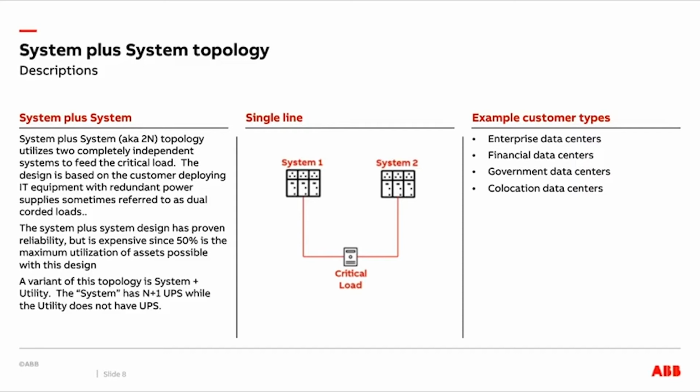Typically, these power supplies share the load equally. The system plus system design eliminates single points of failure and also allows concurrent maintainability. The major drawback is the maximum design utilization is 50%, resulting in a very expensive system. So extremely reliable and extremely expensive. So let's take a deeper look at this system.